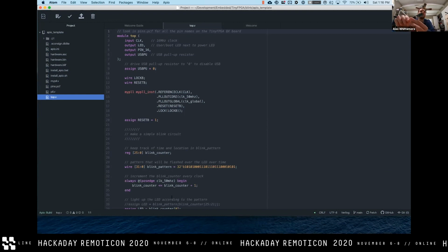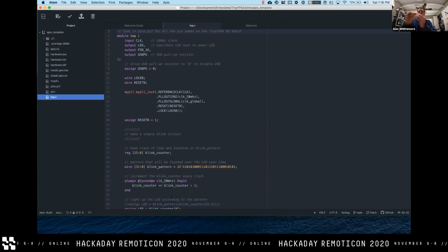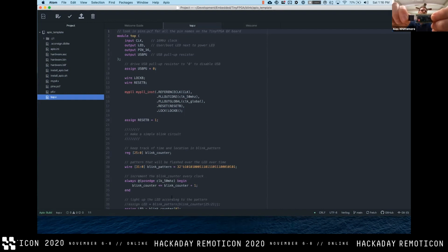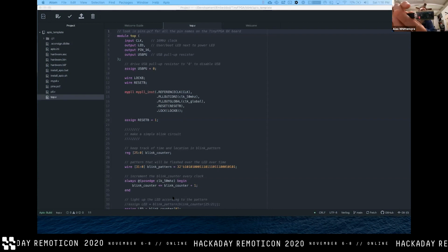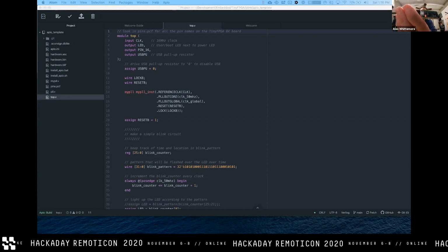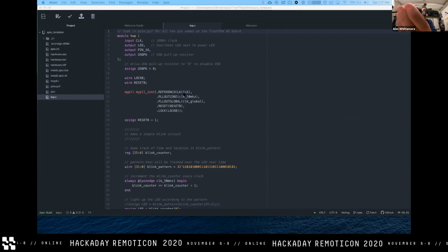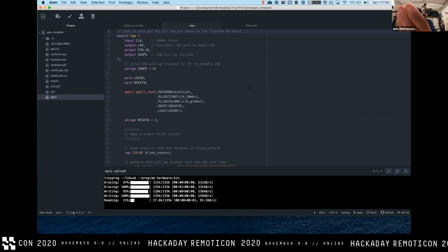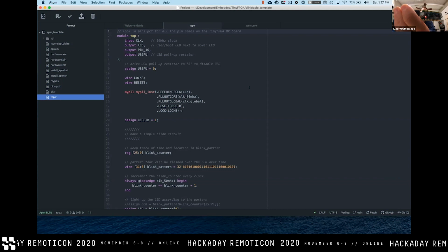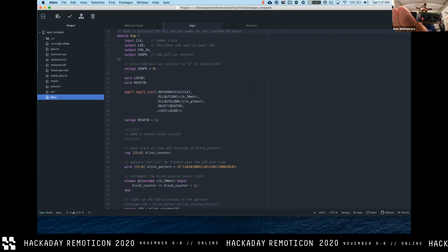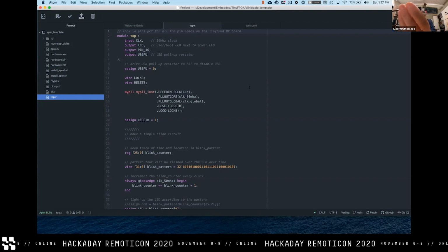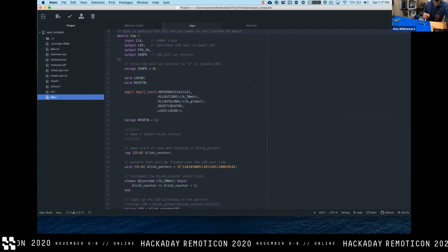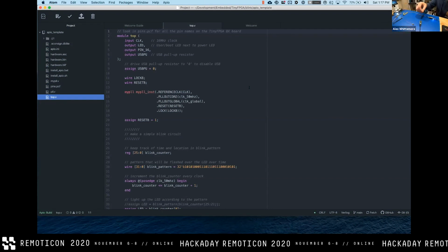I'm actually going to show one thing quickly before I get any farther. So notice how there are 2 LEDs and one of them is lit brightly and the other one is not. Let me reset this. We see that that bottom LED is now pulsating, right? And it's pulsating between 0 brightness and the brightness of the LED adjacent to it. When I go ahead and program this, I just click program again. Basically, it's in bootloader mode. Now it's actually running the gateware. Notice how it's a little bit dimmer. It's dimmer because I'm just blasting a 50 megahertz signal out onto that LED, which, yeah, don't do that or you won't pass emissions.